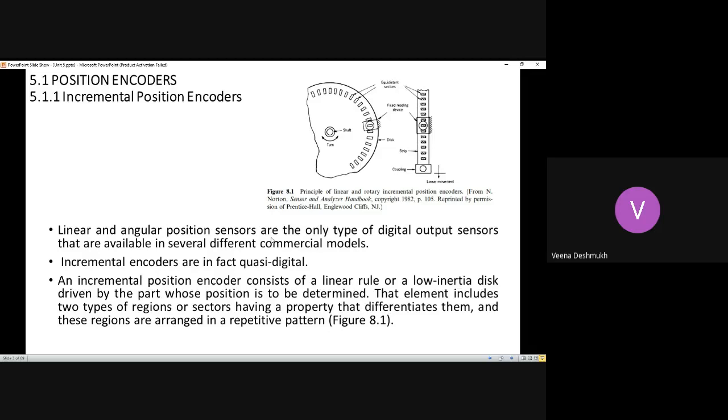And basically they take help of the digital counting mechanism, because here the concentric circles have to be located. If suppose 10 concentric circles are there, and in each of the 10, what is the position? Say for the first one, if I give 0 as the first bit, then third position. So 0, 3 will be the count. On the 0th track, the third position is my count. Like this, digital counting, one for counting the number of tracks, one for counting the exact position. So like this, different counters are used so that the exact position can be located.